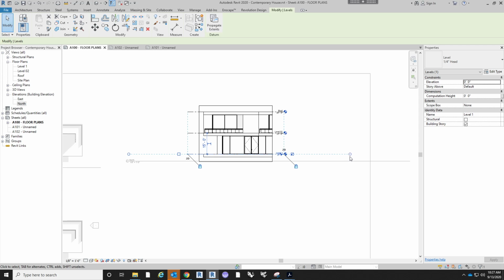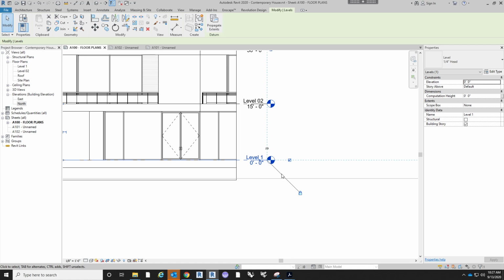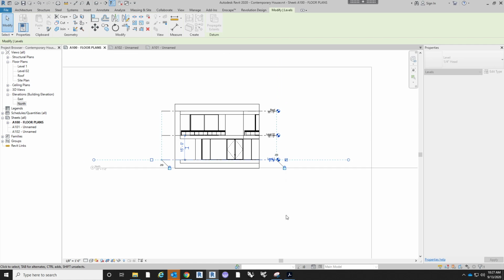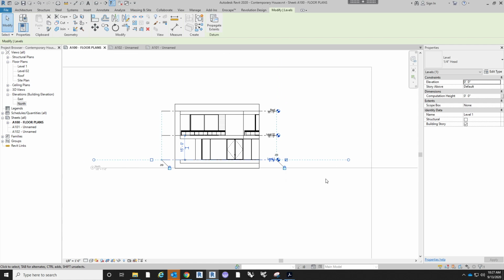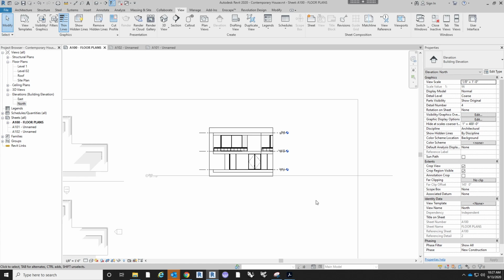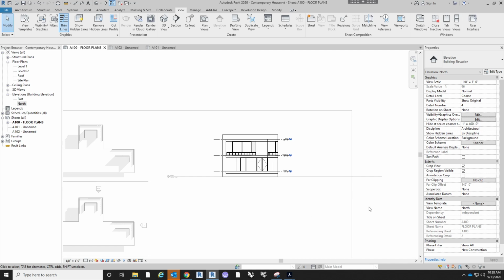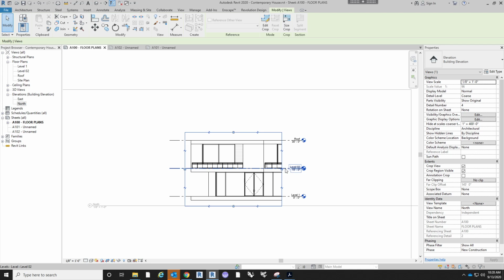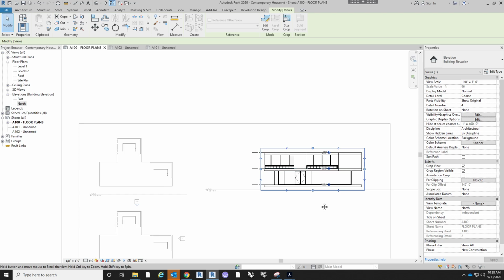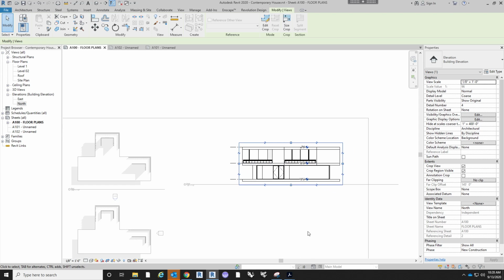the level, you can see that those 2 circles are still on the outside, and now we have just changed the 2D extent, and you can adjust that here, and it doesn't change the overall. It's a really long-winded answer to just say that that's how to move and adjust levels, and just be aware of the 3D versus 2D when you're changing them, because it can have an effect when you go up to set up another drawing, another elevation or a section, etc.